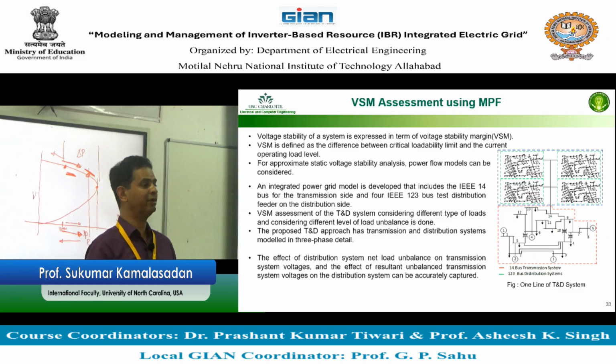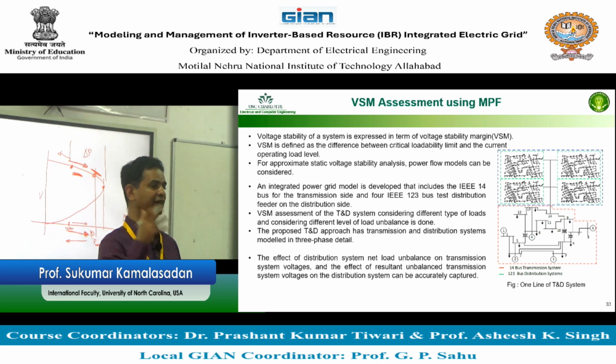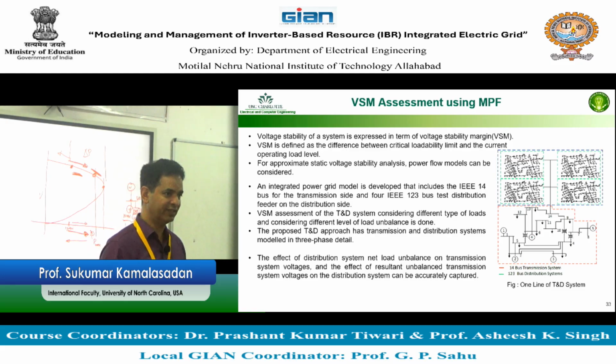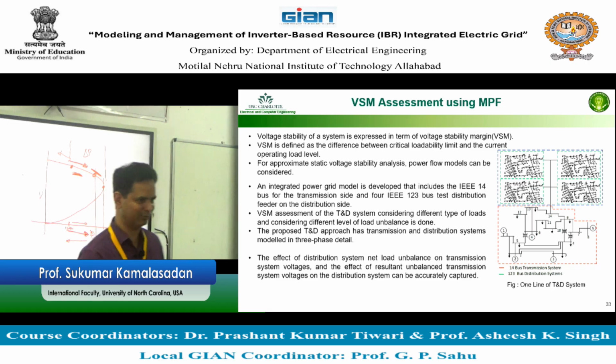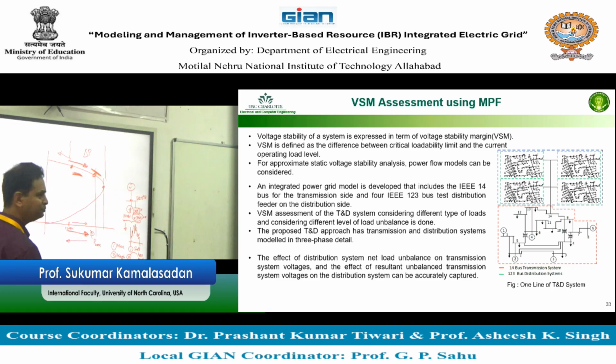But you also want to make sure how much voltage you are going to maintain with the inverter, from the inverter standpoint, the box standpoint, because there is a limit there. You are controlling the voltage at that point. You want to maintain that at 1.03, 1.04. You cannot maintain beyond that with the help of modulation index and everything. So you have to connect with those. That's basically some other research which we have not done, which we can do later.